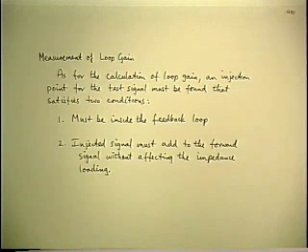And we've already set up most of what we need to do to discuss this, because we've already modified the analysis method looking ahead to the time where we're going to need to measure it, which is principally we don't want to measure T by actually breaking the loop, because in practice that's very hard to do, and we found that the substitute, namely injecting the test signal into the closed loop, was not only a neat analytic technique, but it's also much better when it comes to the experimental end of it. So that's the part of it we're going to follow up now and see how you really do that.